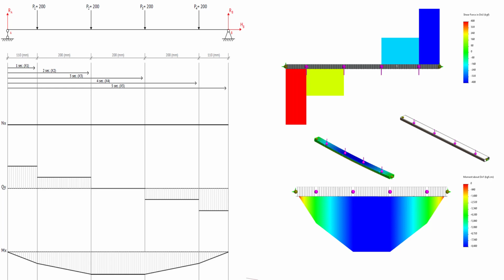And here you could see the shear force, it is 400 kgs. That is the same as the hand calculation we have done. And you could see the shear force diagram here resembles the same. The values are all the same. If I change the unit system and filter the chart options, you're going to get the same, no issues there. In the software we saw the shear force in Newton, so that was showing different answers. That's okay, you can change the unit system and the flow charts.